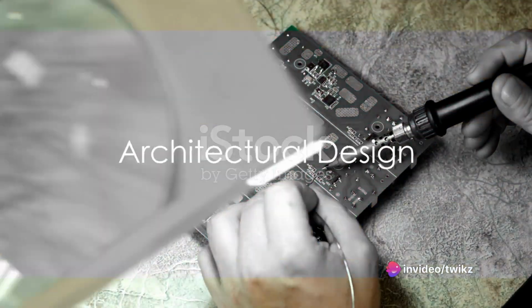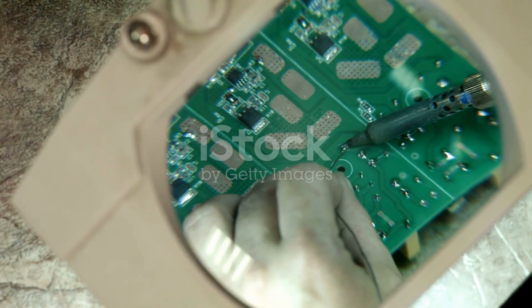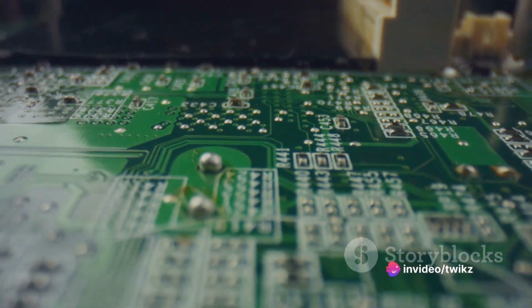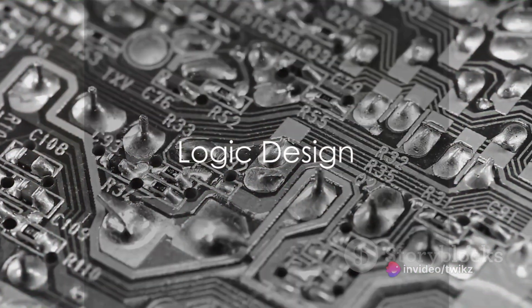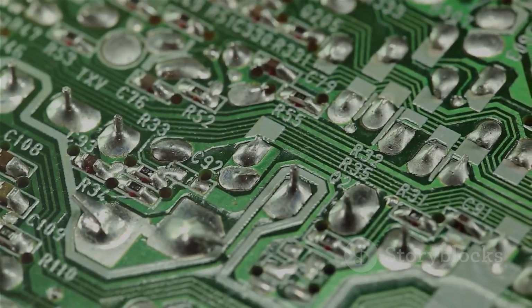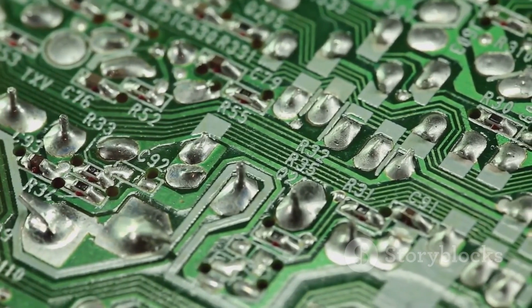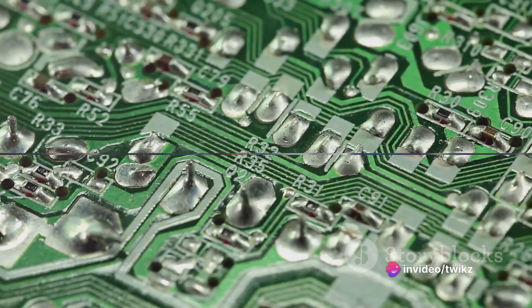Once the system specification is clear, the next step is architectural design. This is where the system is partitioned into several modules based on the specification. Each module is defined by its functionality, and the interaction between them is established. Following the architectural design comes logic design. This stage involves converting the system specifications into a logical structure. In simple terms, it's about defining how the system works, using logic gates and flip-flops.